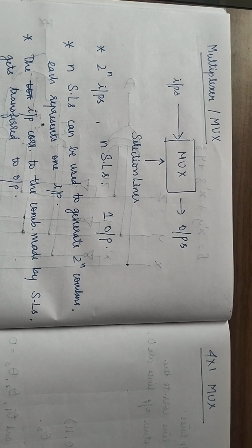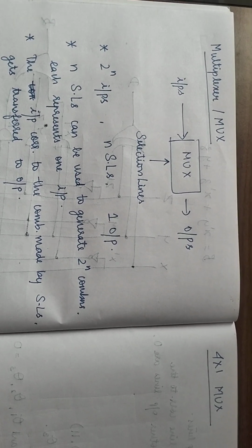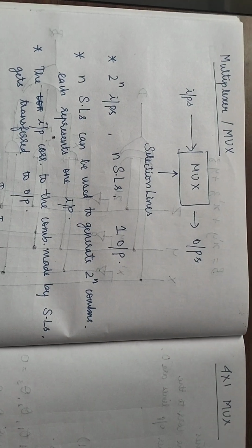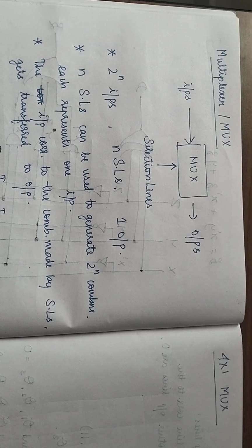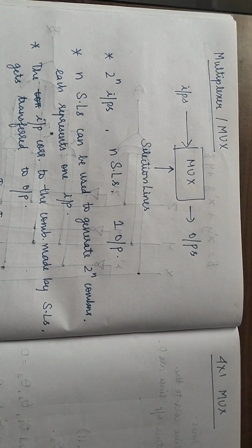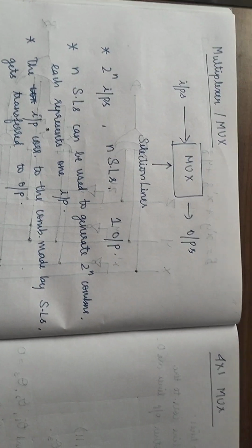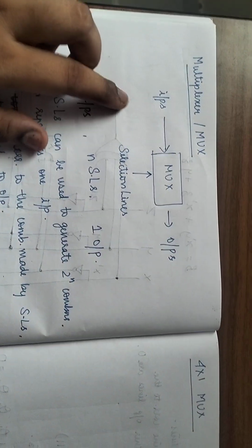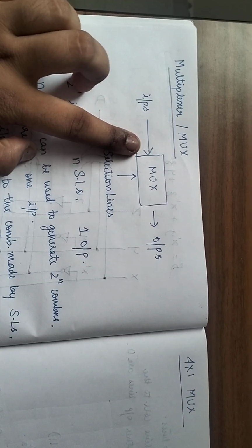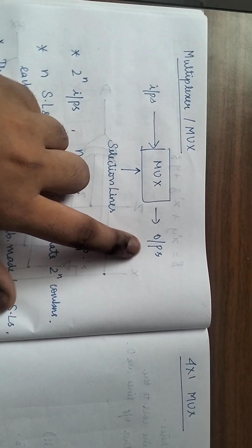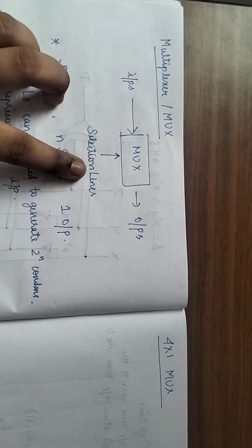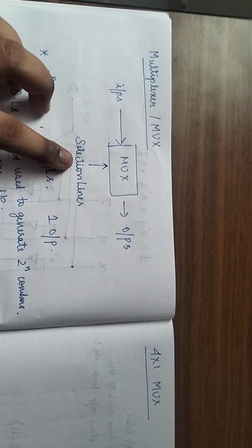In this segment, we are going to be looking at something called a multiplexer. A multiplexer is just another combinational circuit which is, let's say, one notch higher than your normal adders and subtractors. So what happens here, again like any combinational circuit, is you give it some inputs, something happens in the circuitry here and you get some outputs. But apart from the inputs and outputs, you have something called the selection lines.